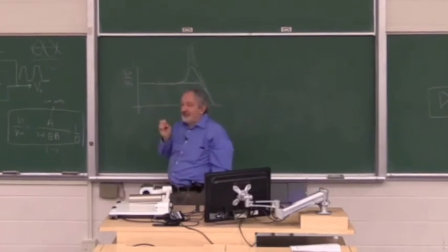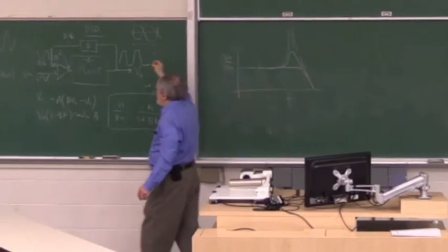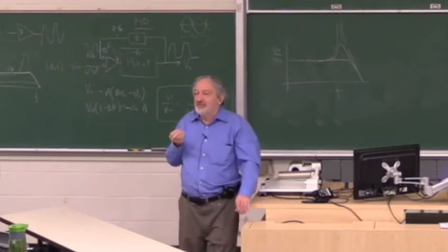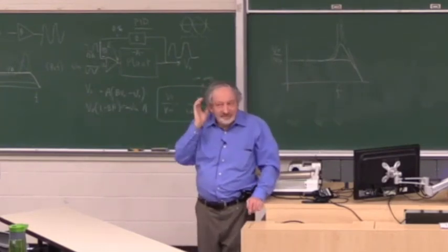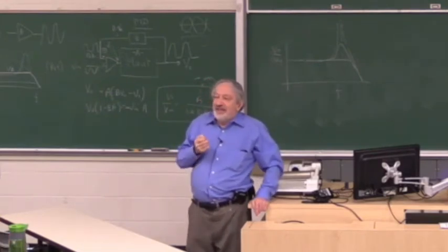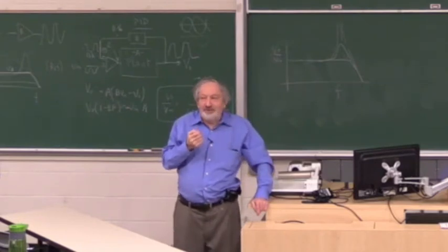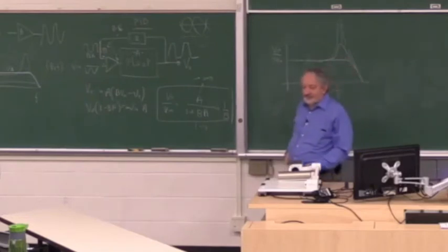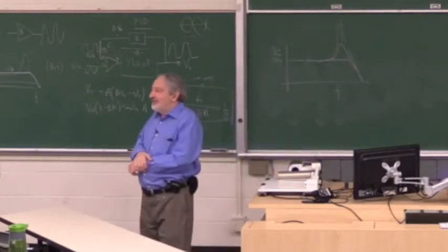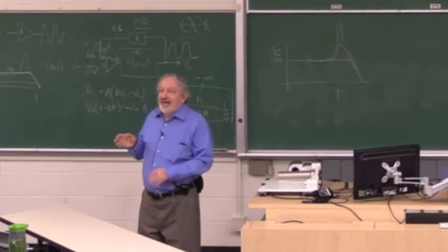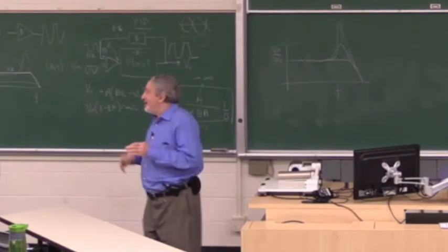So I'll give you a hint. When we talk about phase shift, what is the physical cause of phase shift? What causes phase shift? Delay. Very good. Okay, so several of you answered right. So delay causes phase shift. So now think about it, and now tell me, why would it always oscillate at the end? Yes. And more signal through, so a delay makes it bigger. Very good. Because the higher the frequency, the same delay makes a bigger phase shift.